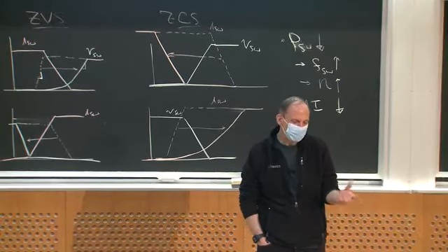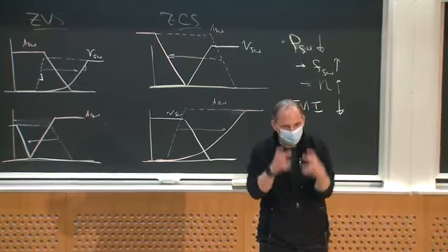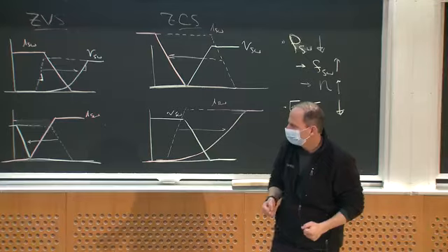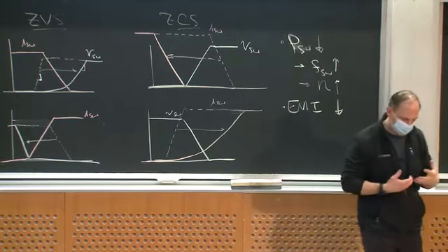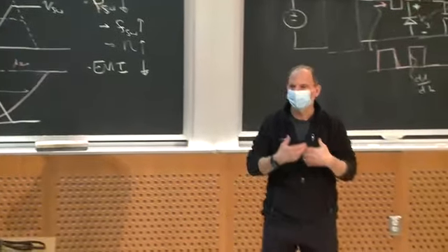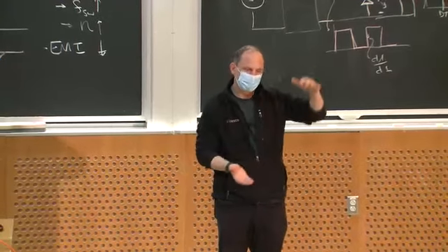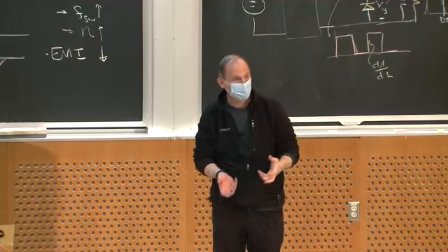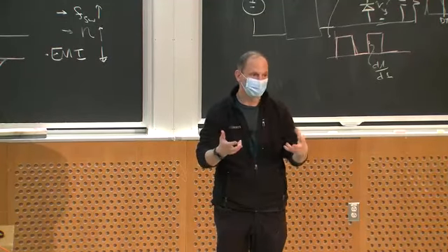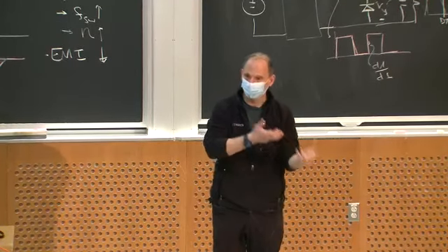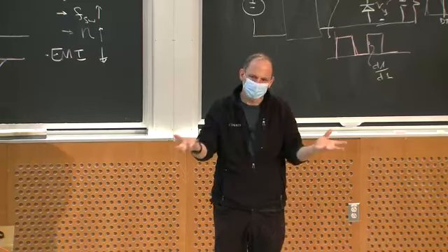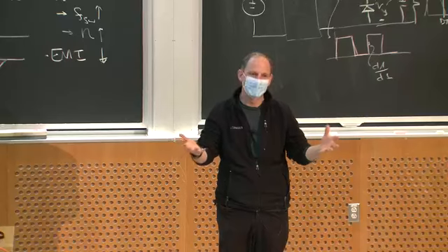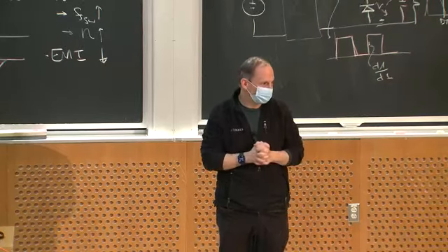So you have to match the soft switching technique to the device type you're using, and you have to match the particular circuit or technique to the circuit application, because it depends upon the voltage range or the power range you want to operate over, which might change which circuit implementation of soft switching is a good idea versus a bad idea. And that's why there are so many different techniques, or versions of the general idea, because there's not one size fits all.